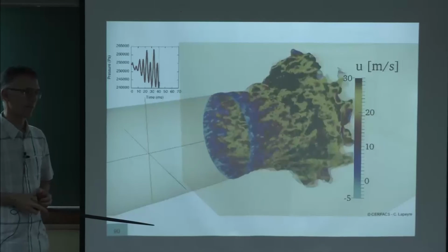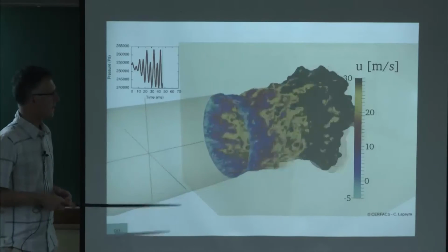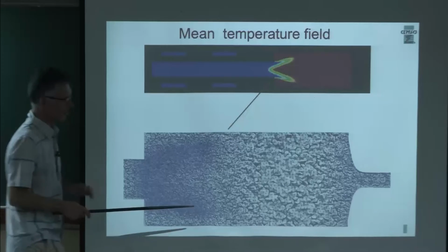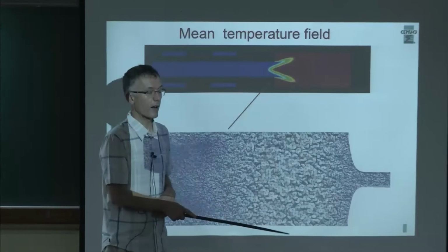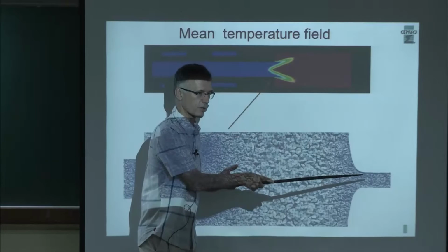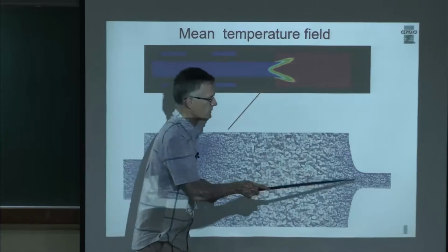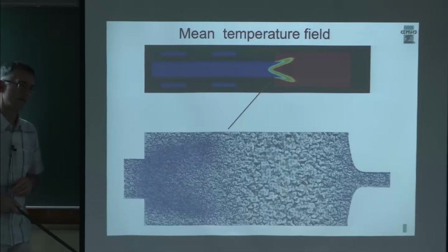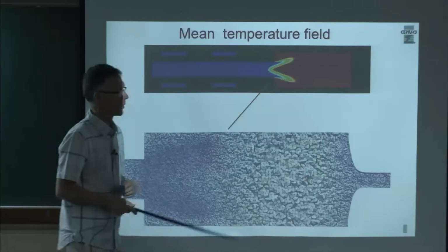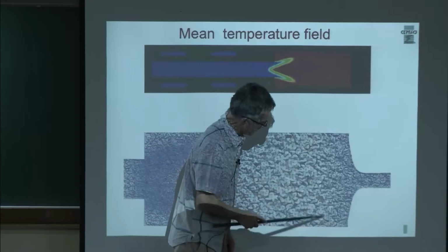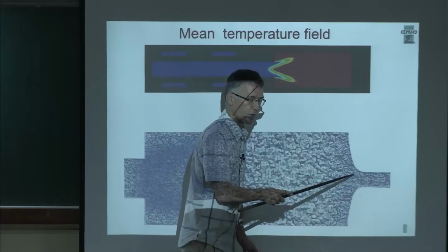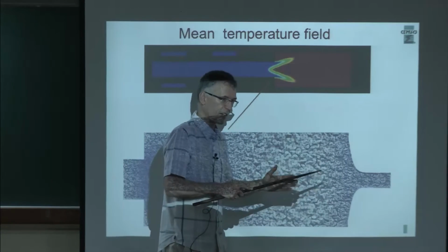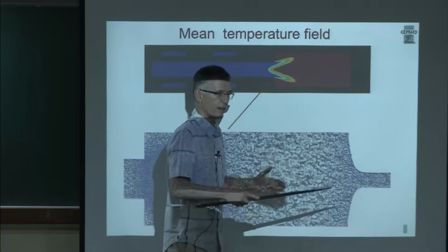So at T equal to 0 actually there's a shift in the parameter. What we do at T equals 0 is we add the nozzle. If you do the simulation without the nozzle, this flow is stable. We are able to stabilize it. We put non-reflecting boundary conditions. We have a stable flame, and then at T equals 0, we add the nozzle, and then this thing goes away. That also changes the mean flow. So the mean flow is also changed, and we assemble it: we cut it here, and we do a simulation of the nozzle for steady flow, we do a simulation of the flame for steady flow, we connect them, and if it would stay steady, it would be a consistent solution, but right away it starts oscillating.